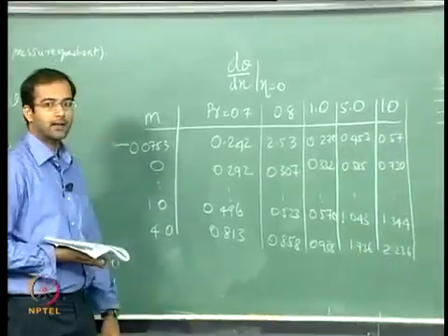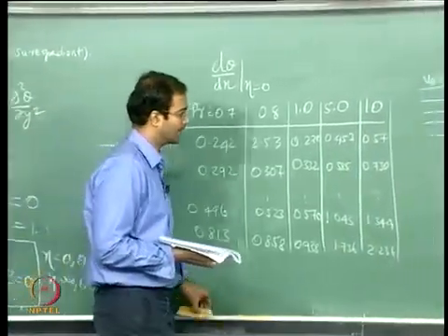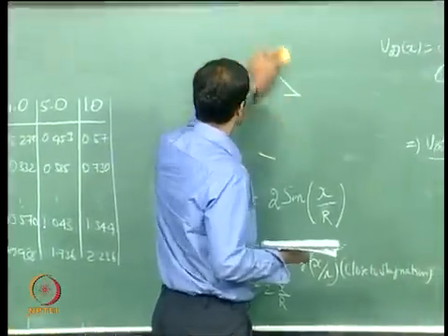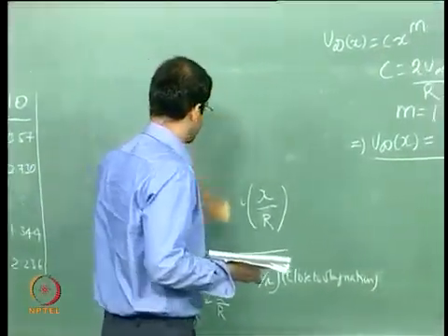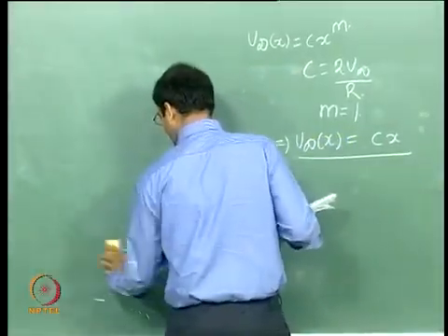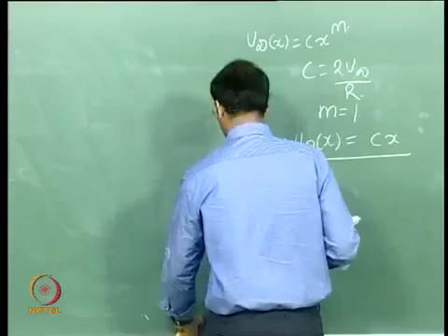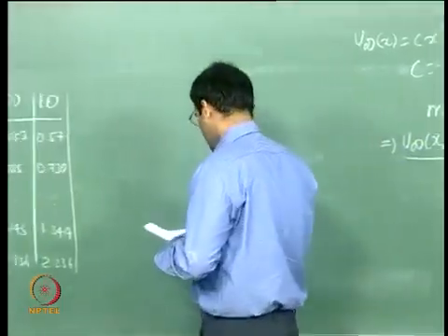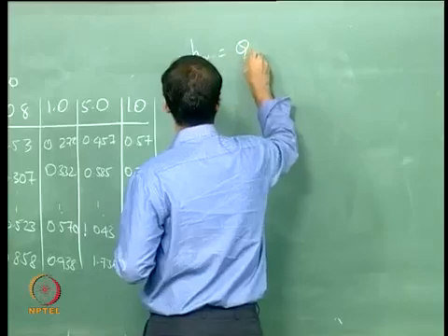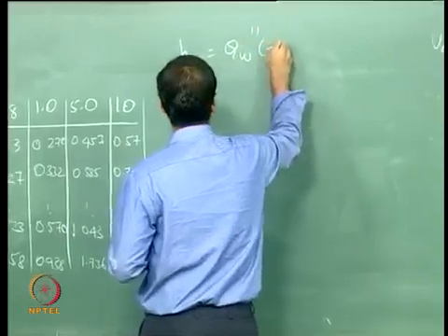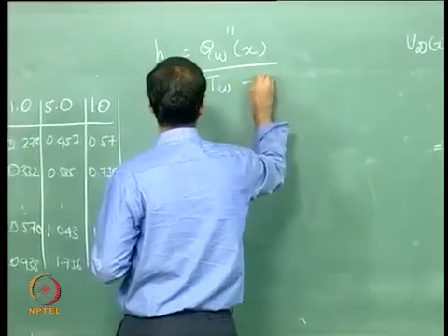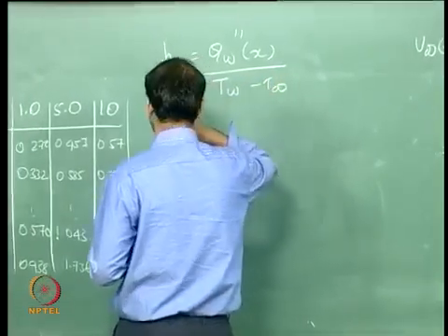So why we are calculating the slope? Okay, so because we finally are interested in the heat transfer coefficient and Nusselt number. So therefore you can define your local heat transfer coefficient the same way, the wall heat flux divided by T wall minus T infinity.